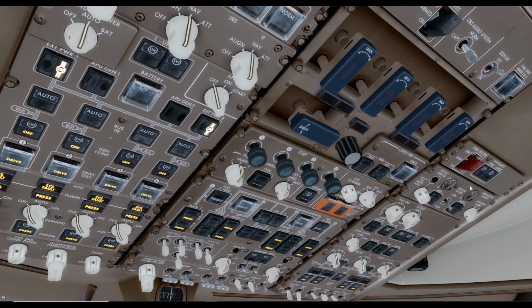making sure that the landing altitude switch should be in the automatic position, so it shouldn't be depressed. The outflow valve left and right switches should be off. The cabin altitude selector should be in normal, and the outflow valves should be showing open, and the position of the valves are shown on these gauges.